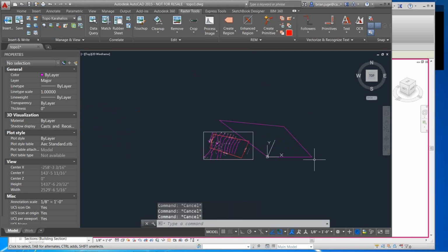Jennifer, you have anything to add? Another better way of doing this in AutoCAD? I'm trying to think. Is there an origin command? You can set your origin closer to your site instead of moving your site closer to your origin. There used to be. Is it HP origin? HP just handles hatches, I believe.